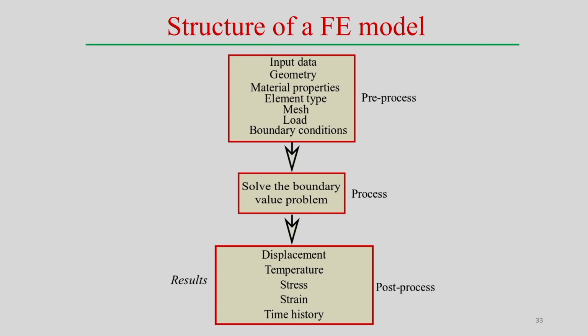Now, the processing solves the boundary value problem, or rather, I can say the finite element problem. The whole thing finally forms a linear system of equations, and it solves the linear system to get the output at each and every node point. The results can come in the form of a displacement field or a temperature field, also stress and strain, and even the time temperature history. All sorts of results we can find out in the post processing part.